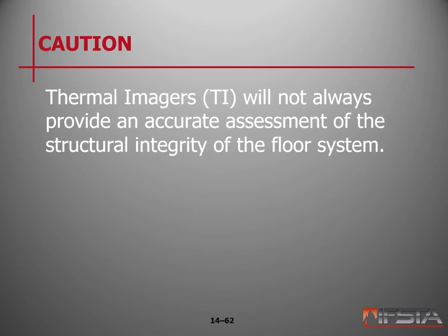Thermal imagers will not always provide an accurate assessment of the integrity of the structure of the floor system. Remember that thermal imaging cameras are great tools, but they show the difference in temperature of what you're looking at. So it's either cooler than the air, or the air is cooler than the object, as an example. So it's showing you temperature and the difference in the temperature of those things.